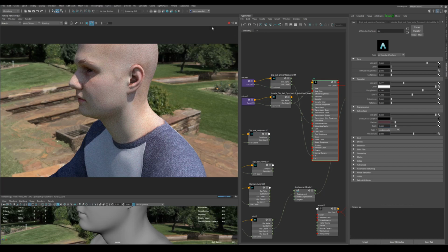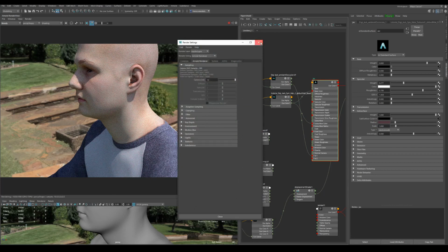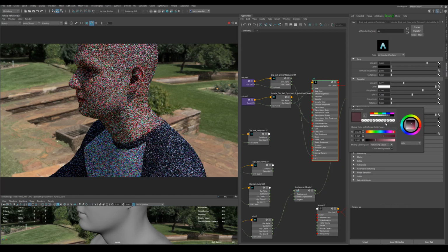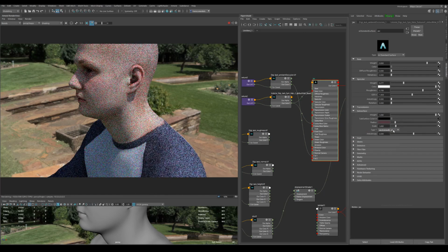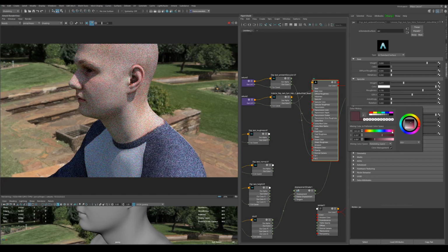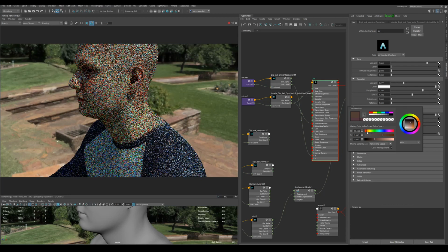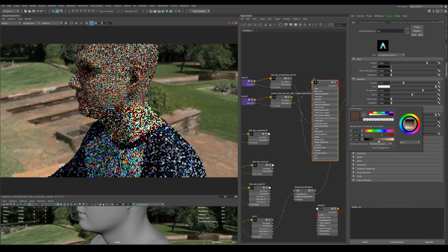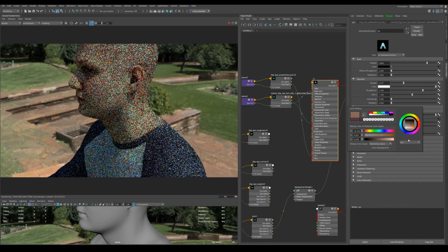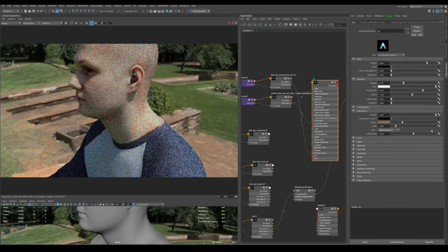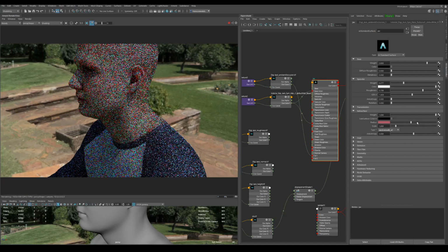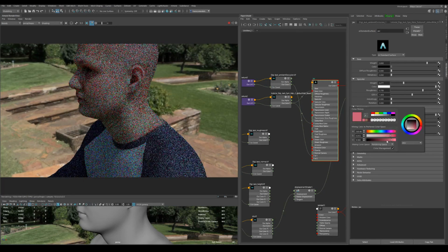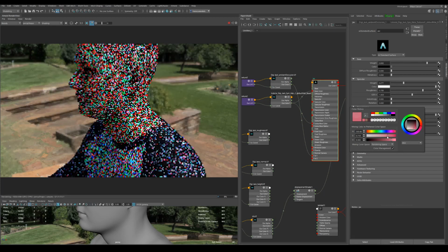However, this takes a lot longer to render. Especially with the new Random Walk 2. I'd actually change the hue of this to slightly more of my skin colour, and brighten it up a lot as well. So the brighter it is, the more light will go through it. And it's usually good to pick a more red tone, although I'm going to desaturate a little bit.